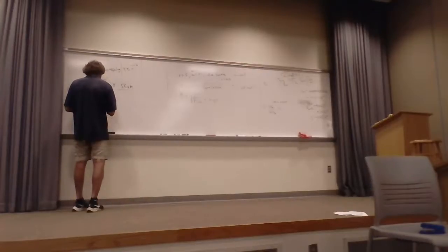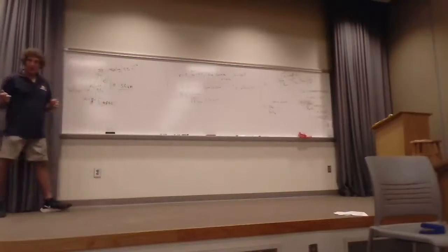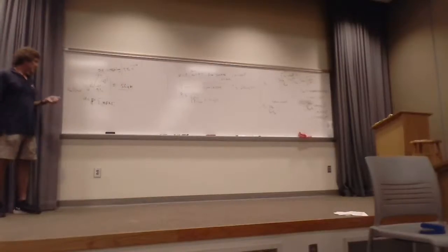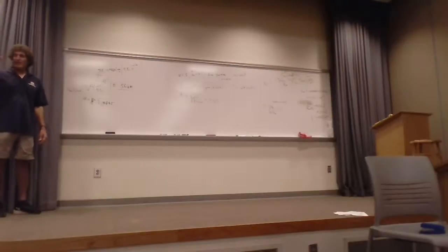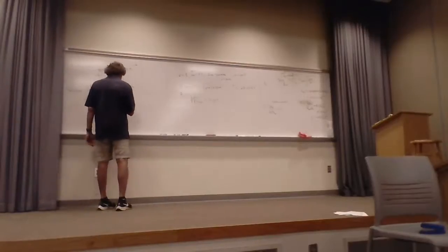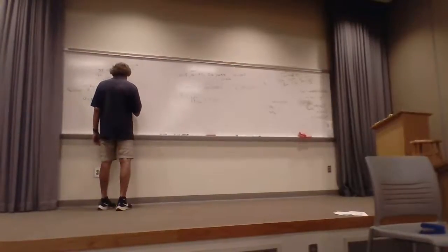It's just going to be equal to the square root of pi f mu sigma, right? That's the one that we talked about. It's 1 over skin depth is alpha. It's the square root of pi f mu sigma, and it's a big number. You can give that to me if you want. I forgot what it is. Huh? 4.735 times 10 to the 5.